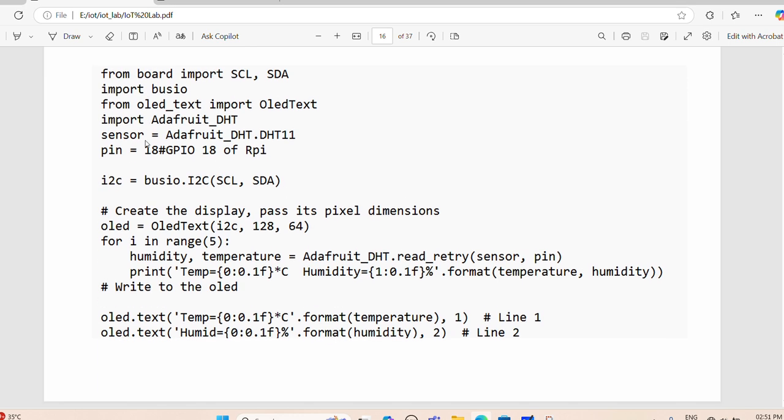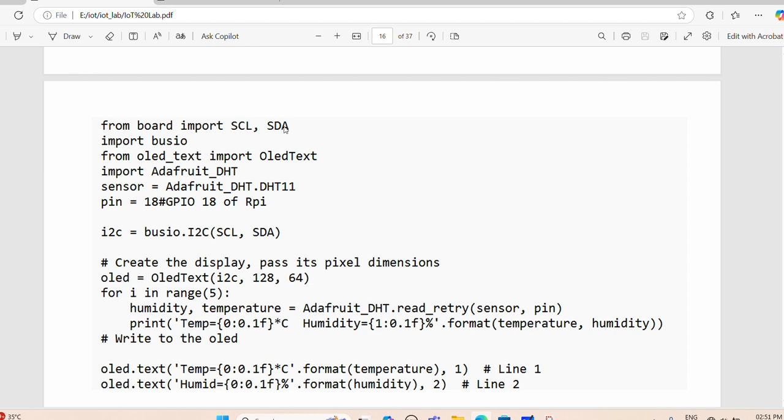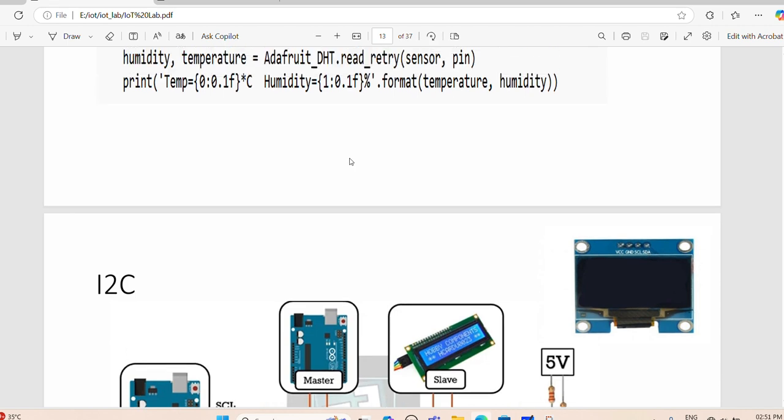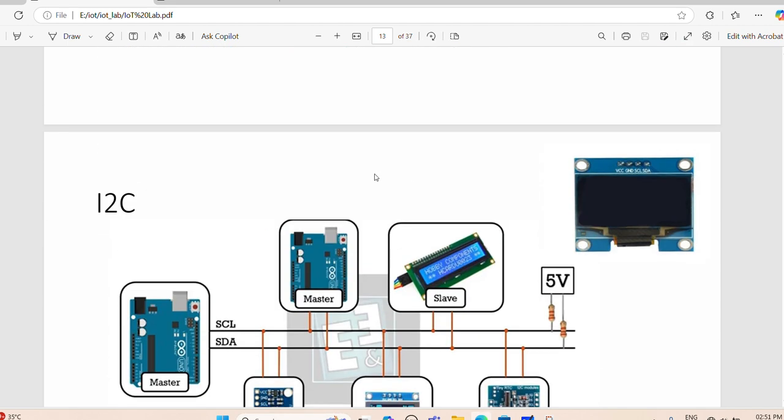And this is a program which has both the OLED interfaced as well as the temperature sensor connected. So here, the OLED system, which is this, has got 4 pins: SCL, SDA, ground and VCC. Make sure that the VCC, the supply voltage for triggering this OLED, is 5 volt. Either you can use pin number 2 or pin number 4. For ground you can use pin number 39.